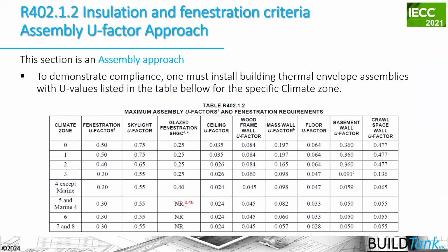So we do have a U value table in our energy codes, but the reality is that the U value table, or U factor table, is describing the assembly of our wood framed wall, in this case, in climate zone 5, but its primary purpose is for the utilization of energy modeling software.